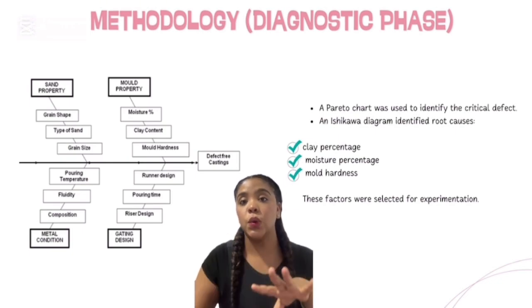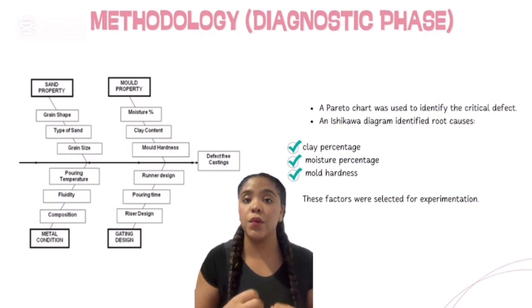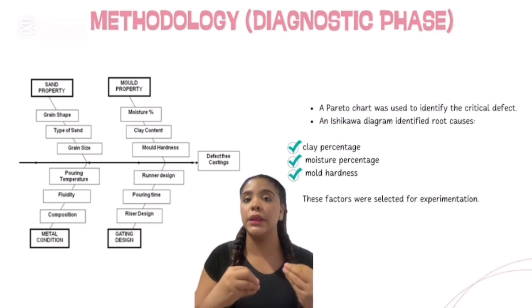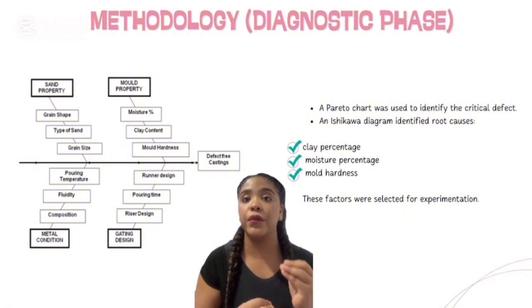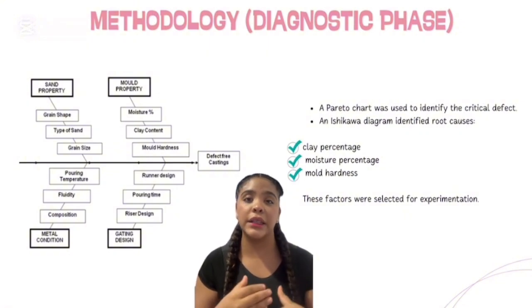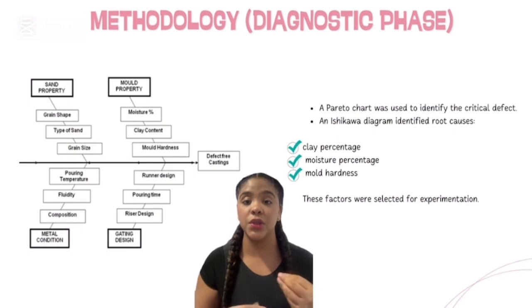The analysis showed that the predominant defect was the blowhole, a type of internal cavity or bubble that significantly affects the integrity of the piece. This result confirmed that there was a critical issue in the process, generating rework, economic losses, and decreased production efficiency.